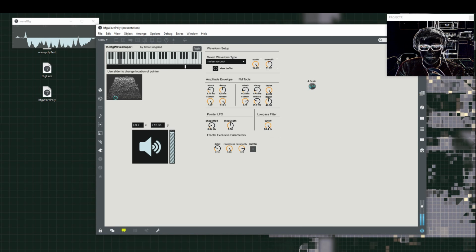We'll hear the variance more, and it's like we can almost hear the points as the buffer updates. So we're no longer interpolating between the buffers, but we're just hearing each one along the path, which is a neat effect at certain times. If we want something smoother, we want to turn that interpolation up. I actually like to leave the interpolation around 10 or 11%.